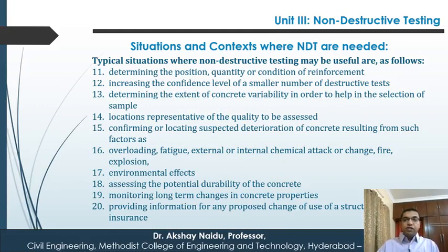Now, determining the position, quality and condition of reinforcement. We have to identify reinforcement location without damaging the concrete. So an NDT will be useful for that. Increasing the confidence level of a small number of destructive tests. Determining the extent of concrete variability in order to help the selection of sample locations representative of the quality to be assessed.